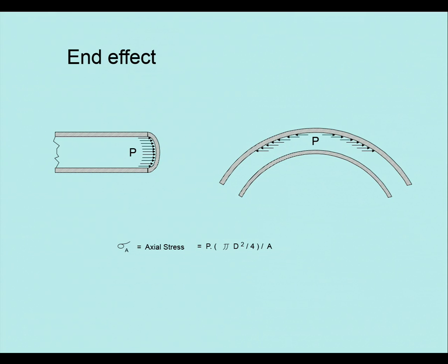So, but also when you've got, this is overemphasised, a pipe around a bend, whether it's an elbow on a spool piece or a riser, or a curve in a pipe, and I've got a pressure on the inside, that pressure will act on an equivalent internal area and try to put forces that way. So that's the end effect there. It doesn't have to be the very end. In the middle of a pipe that's got a curve, there can be an end effect in the pipe.